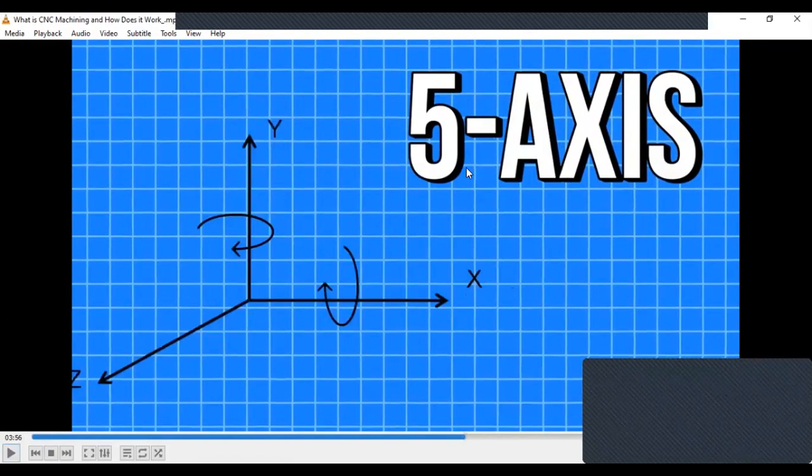Now, do you understand what that 5-axis machine means? That is generally what we see for complex geometries. The word 5-axis machine is being used quite often. Those machines will have 5 axes. So it basically indicates the degrees of freedom that are allowed, right? Not just can they translate in X, Y, and Z, they can also rotate about any other 2 axes, generally X and Y.